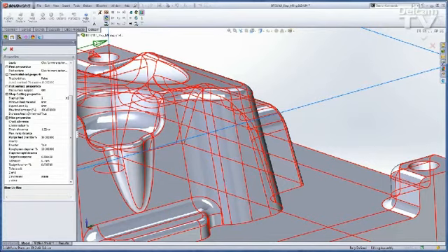And we have this maximum feed rate. I mentioned that it will increase the feed rate with the intermediate steps. You see that enabled here with true. You can disable that, by the way. And this gives it a ceiling, 400% of the programmed feed rate.